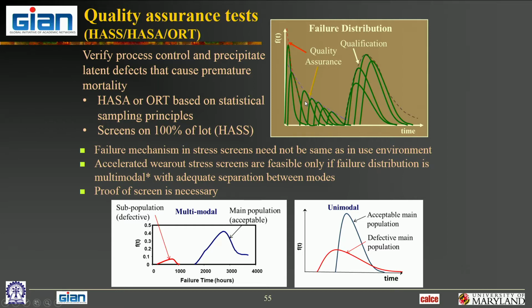You will never see screening in high volume unless I get a known defective batch that's been shipped by some supplier of a part or a subassembly, and we discover there's a problem in it. We sometimes screen those if there are non-stress screens available. So visual inspection, bad piece, good piece, there's no stress, that's fine. Or just a functional test without applying a lot of stress. This one is out of spec, bad; this one is within spec, I'll take it. So non-stress screens are allowed.